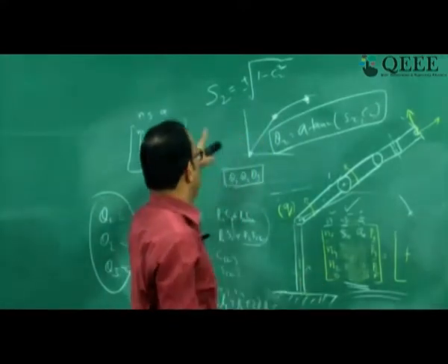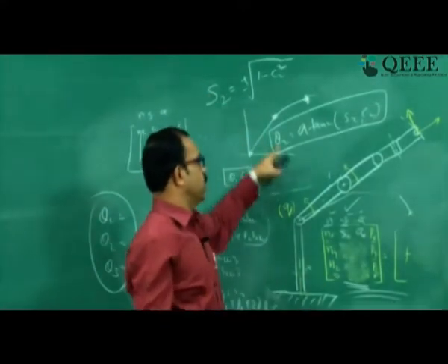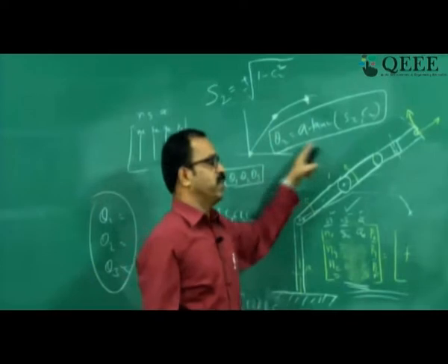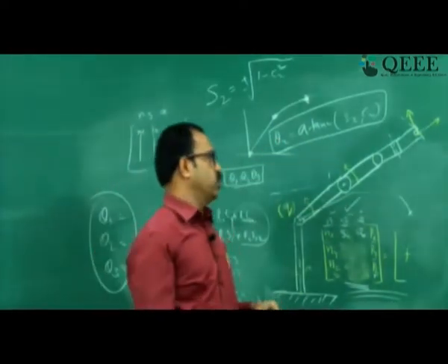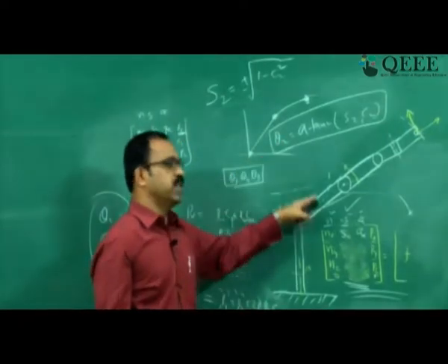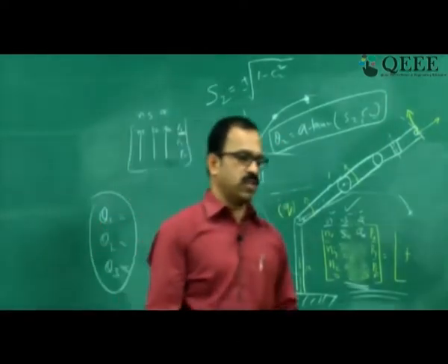And of course we have 2 values for sin theta 2. So therefore we will be able to get 2 values of theta 2, and then depending on the joint angle limitations you have to choose one of the joint values for theta 2. So that is the way you get theta 2 for this one. So first we will solve for theta 2.